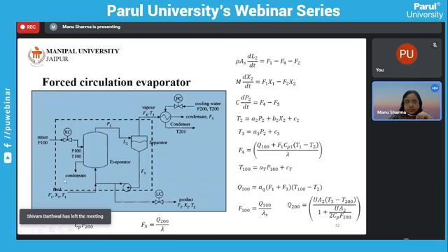So for this process, I have assumed that the evaporator plus a separator is the system. For this system, these are the set of mathematical equations based on the conservation principles. Here we have seen the variation of liquid level in the separator with respect to time, variation of the composition with respect to time, and variation of the pressure with respect to time. So these are the 3 basic equations accompanied with certain constitutive relations. So here we are having differential algebraic equations.